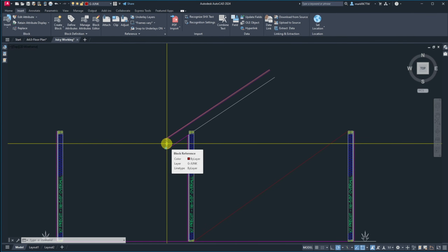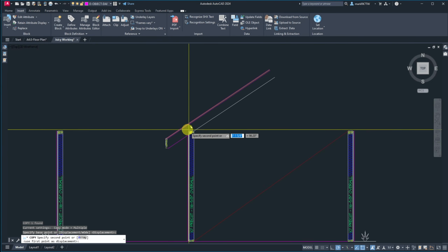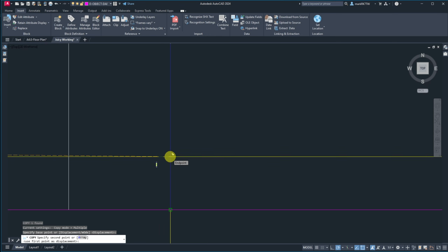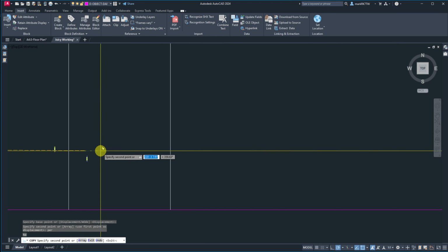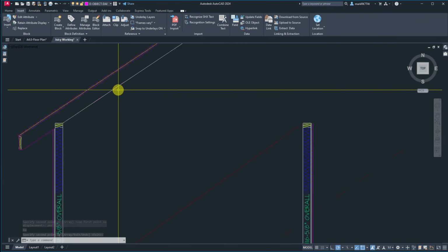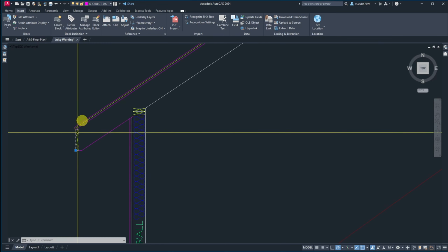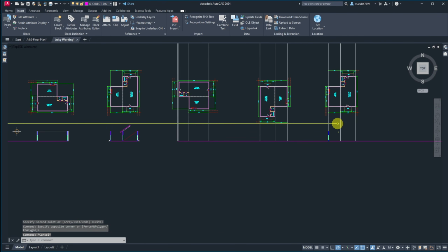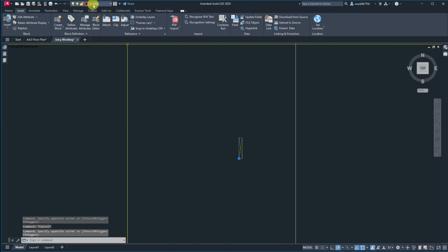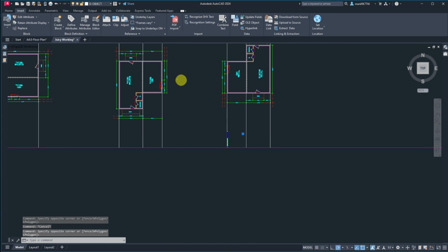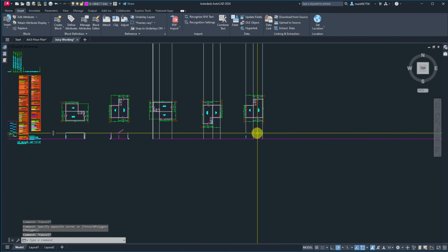And so let's just copy it from here and put it in our section. So I'm going to put it perpendicular, and I think it's this one. So that should end, yeah, that's it. Should end up in the right place when we rebuild this, and it's on the right layer before I switch this to where it won't print. Oh, it is on the junk layer. You know what? I inserted it on the junk layer, so this one will be too. So that would have been an error, not discovered until I tried to print my section. But now it's on the right layer, so if I grab it, it is the object. So we're good there.